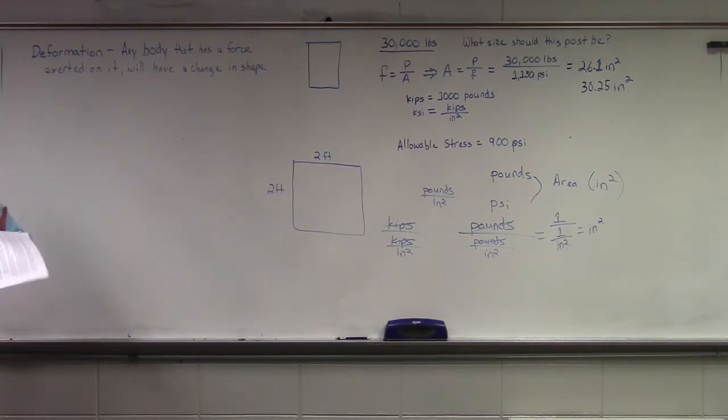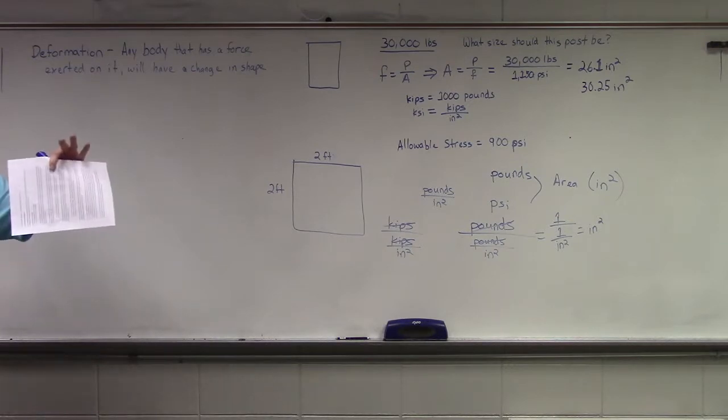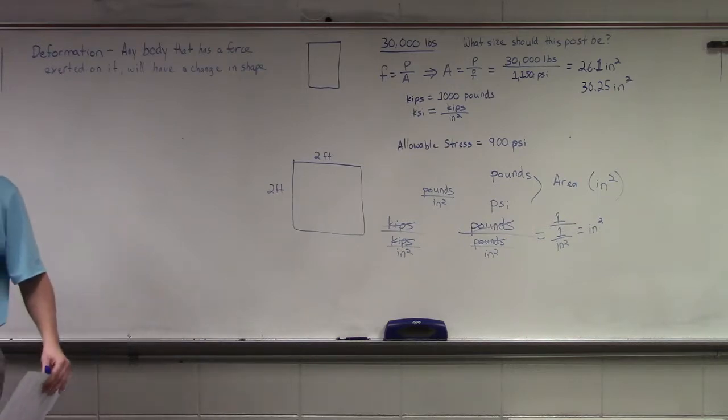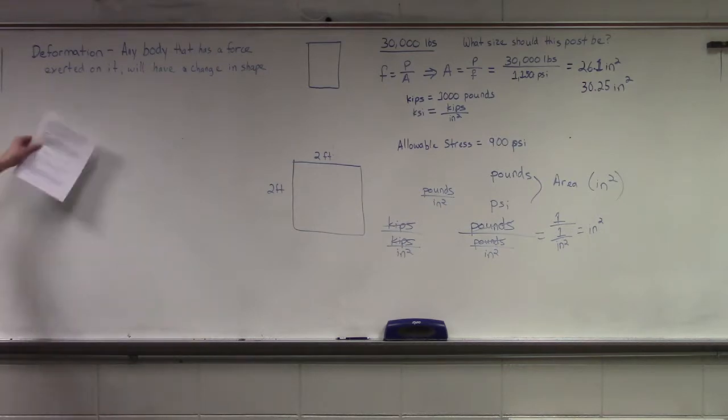We have to be mindful that if we have too much deflection in the joists of a house, what could we potentially impact? The joists themselves might be fine. Ceiling material? Yeah, we may start cracking joints in the sheetrock. If we have larger deflections in larger buildings, we may have issues with mortar joints. We may have issues with doorways. So we have to make sure that we're aware of what's going on with our deformations.